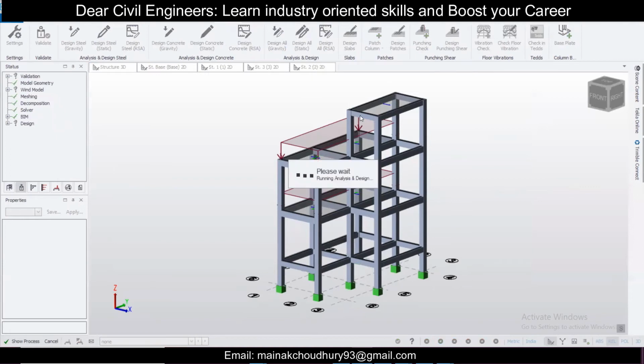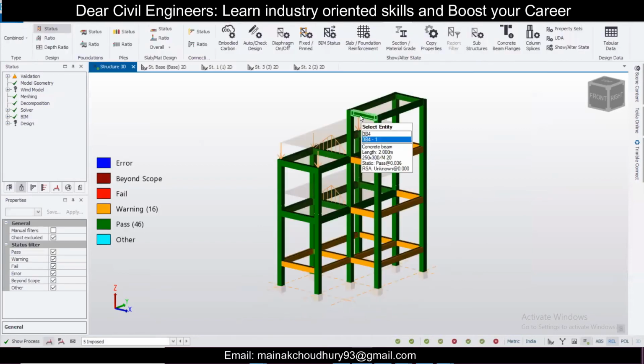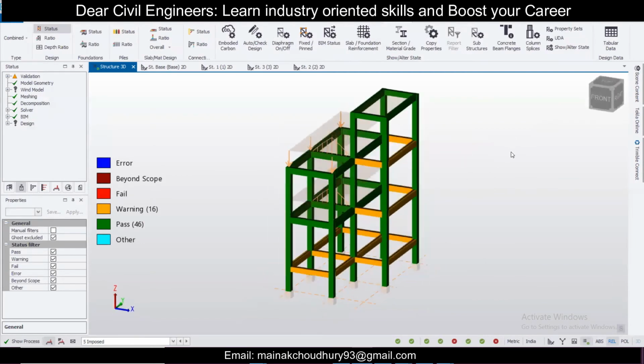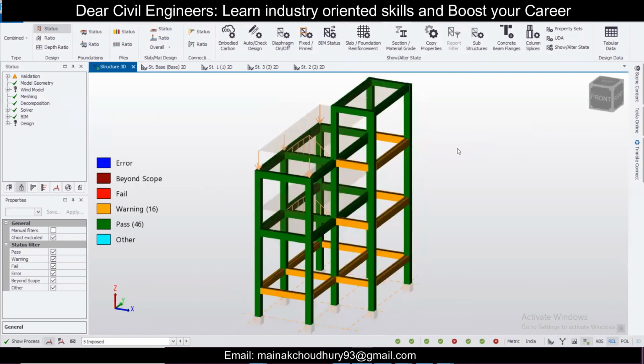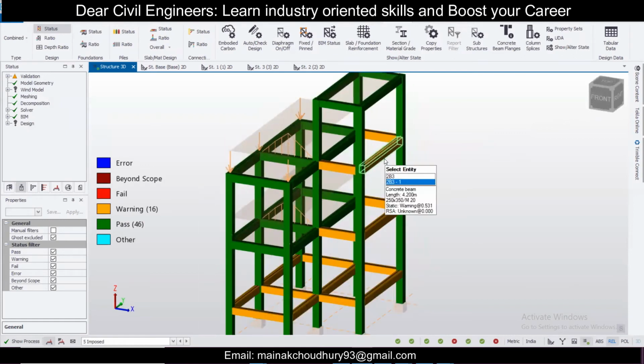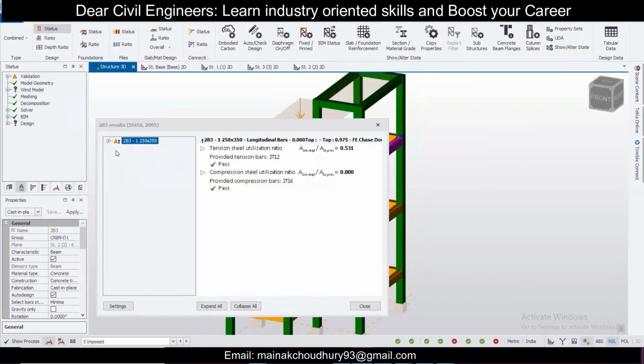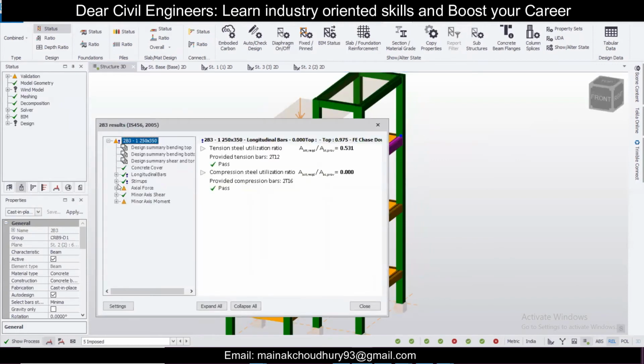It will take some time depending on the model, but since it's a very small model, and it covers pretty much every aspect here, you don't need to worry. Now, as you can see, almost all have been designed here. Let's see what the warning is here. Just right click on this particular member and then check member static. Let's see what warning has been given.